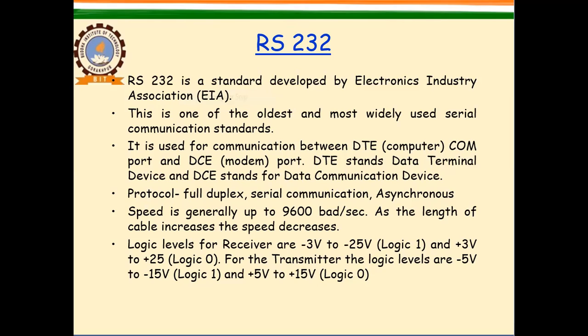It is used for communication between DTE, that is the transmitting device, maybe a computer, maybe a controller, and DCE, meaning the actual device from where the data is going to be transmitted, meaning the data is generated and then transmitted. DTE stands for data terminal equipment, and DCE stands for data communication equipment. So DTE is the device which actually produces the data, and it is the device which